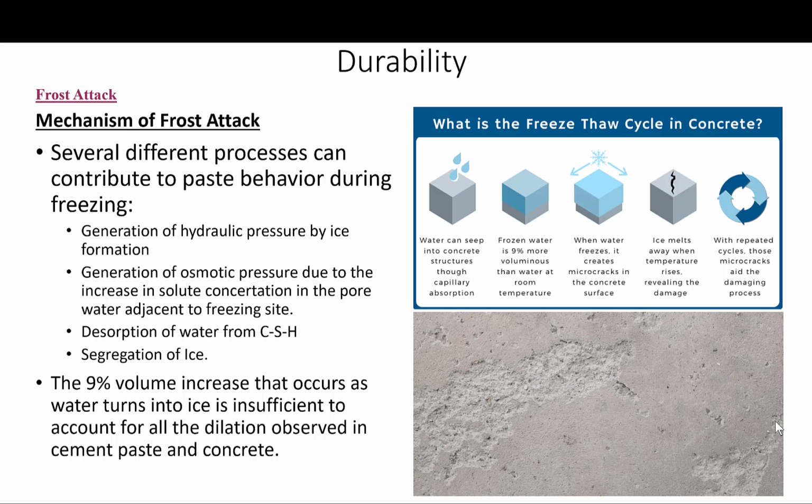For many years, the major contributor to dilation was believed to be hydraulic pressure, as was proposed by T.C. Powers. He explained that as ice forms in a capillary, the accompanying volume increase causes the residual water to be compressed, and this pressure can only be relieved if the water can escape from the capillary to a free space by diffusing through unfrozen pores. However, if the water has too far to move to an escape boundary, the capillary will tend to dilate and the surrounding material will come under stress, eventually causing a tensile failure.